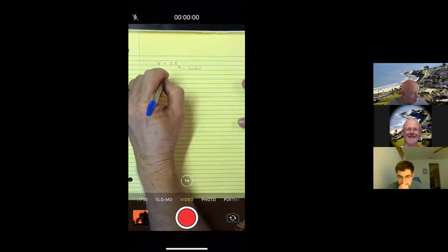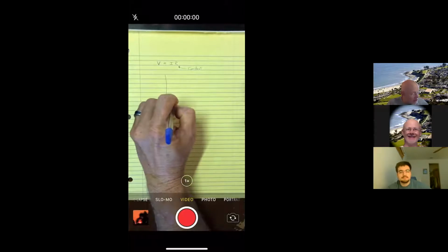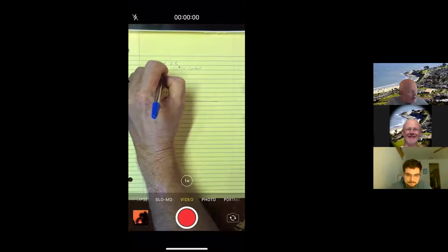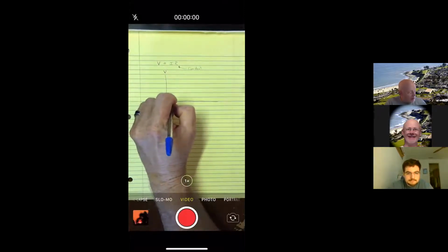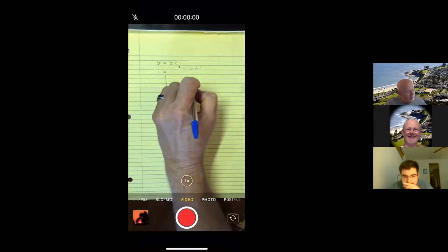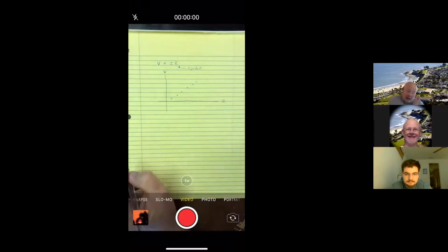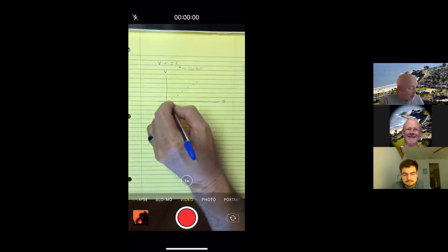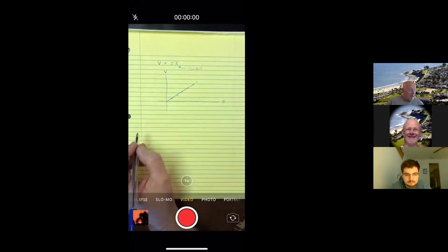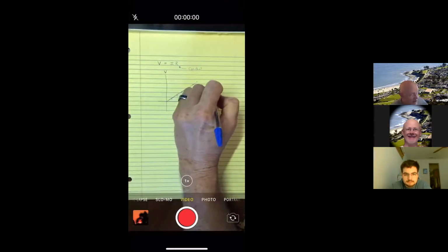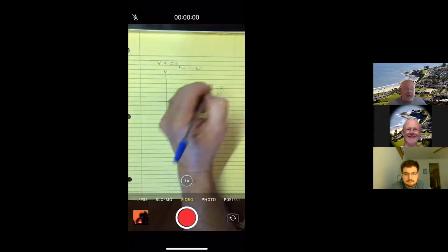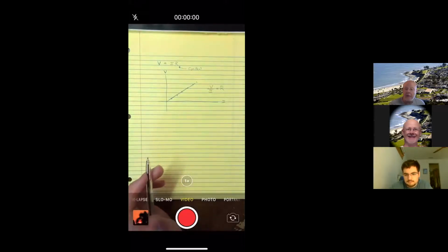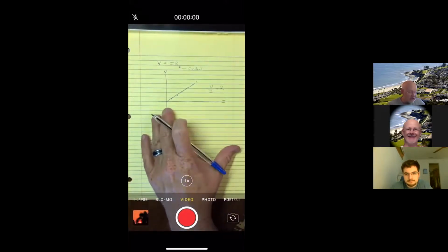Okay, so if I were to make a graph, again, just like you did in the lab, where you have some kind of power supply where you can change its voltage, and so if you up the voltage, you up the current, and it always does it by the same factor. That means this resistance here would be a constant. On a graph, you would get a straight line. And of course, what that means, if you were to take the voltage and divide it by the current, you would always get that same number. And that's what we saw with the blue and the red resistor in the lab. Yeah. They always kept the same.